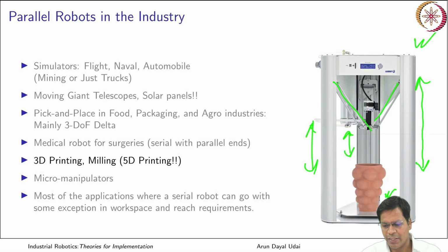As it is built layer over layer, all the 3 links can go up, and by adjusting the lengths of all the 3 links, L1, L2 and L3, which can extend and retract, those are prismatic joints basically.